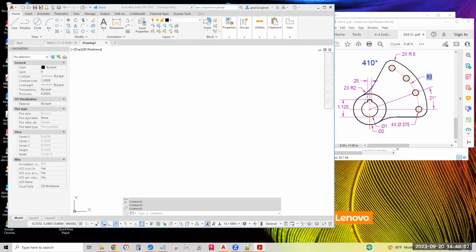Click activate AutoCAD, click on circle center diameter icon. And as always, got dynamic input, polar tracking set for 90, object snaps on with the usual 5: end, mid, center, quadrant, and intersection. Every other status bar is off, and all status bar buttons are shown. Center diameter circle. Click in open space somewhere. The small shaft hole is diameter of 1 unit.